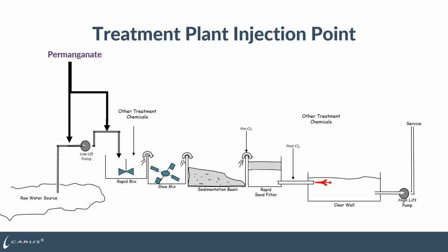for your permanganate reaction. Because organics react a little slower, we do want some reaction time. So typically we want a minimum of 15 minutes, and ideally somewhere in the 15 to 30 minutes of reaction time to react with those organics, plus everything else that might be in the water.